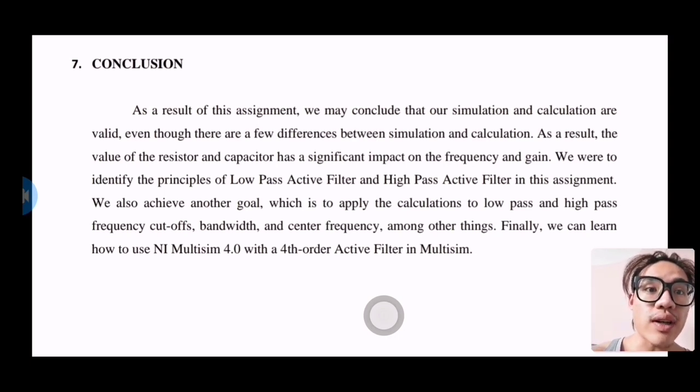We also achieved another goal, which is to apply the calculation to low-pass and high-pass frequency cutoff, bandwidth, and center frequency. Finally, we learned how to use NI Multisim 14.0 with an active filter in Multisim.